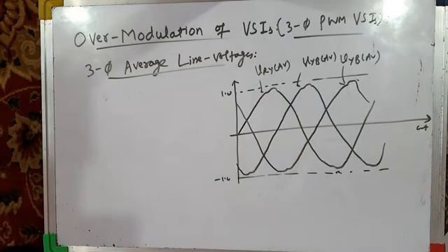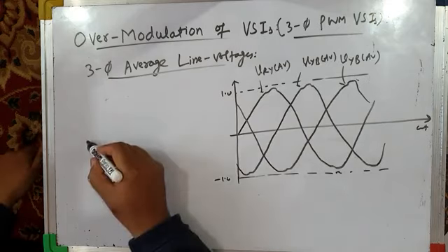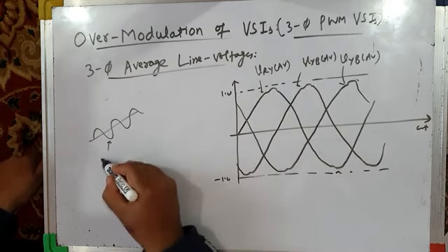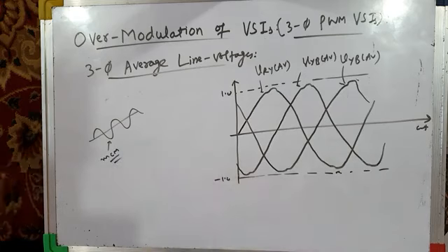This pole voltage distortion is there in the third harmonic injection PWM technique also, because in third harmonic injection PWM technique, a triple frequency common mode signal MCM is injected. And similarly in bus clamping PWM techniques, we inject common mode signals which make pole voltages distorted.